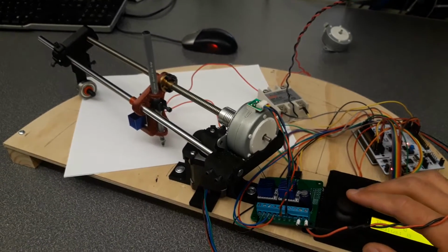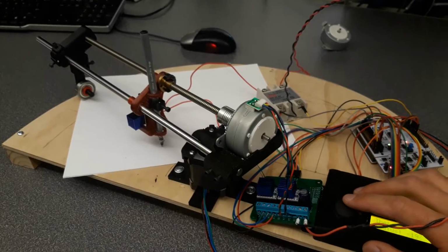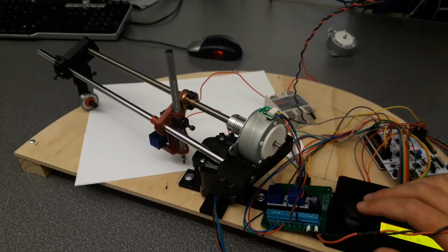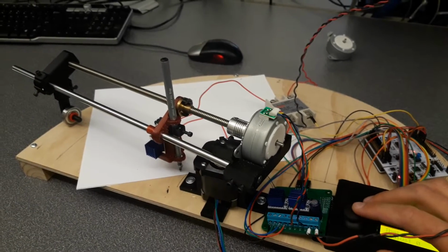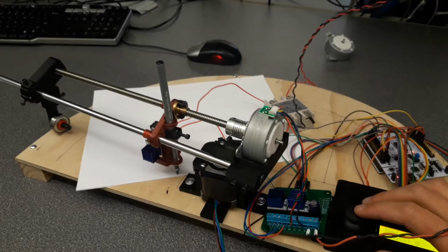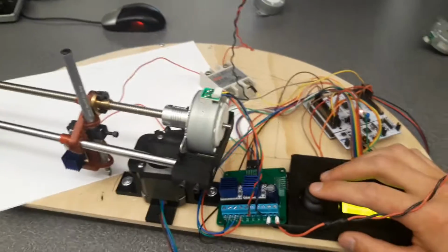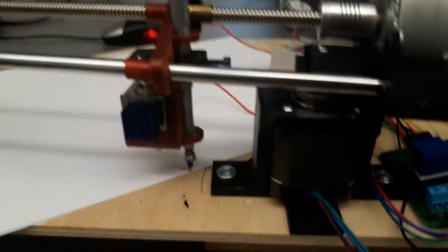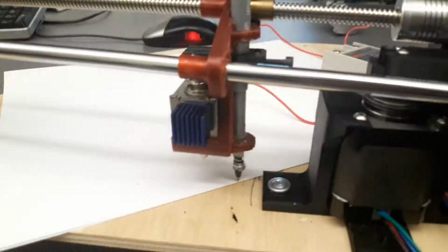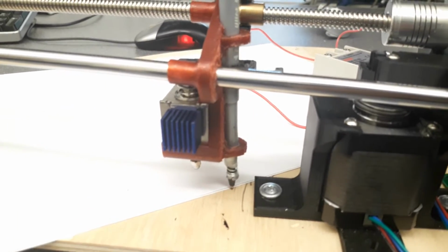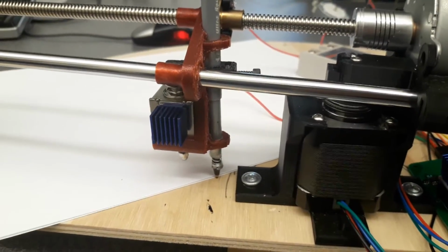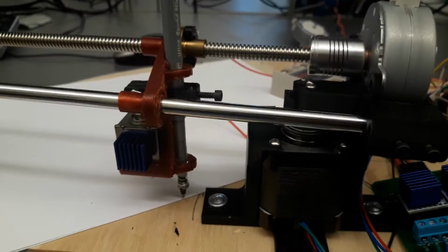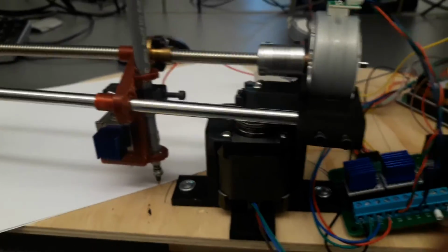See, I'm moving the pen right now. Move it back. Moving it close to the edge, back to its homing position. You can also click the joystick to activate the solenoid, and this forces the pen down to draw the images. So you can see that it is making contact, and I press it again to release. So you click it and then move the joystick to draw the image that you want, and click it when you're done.